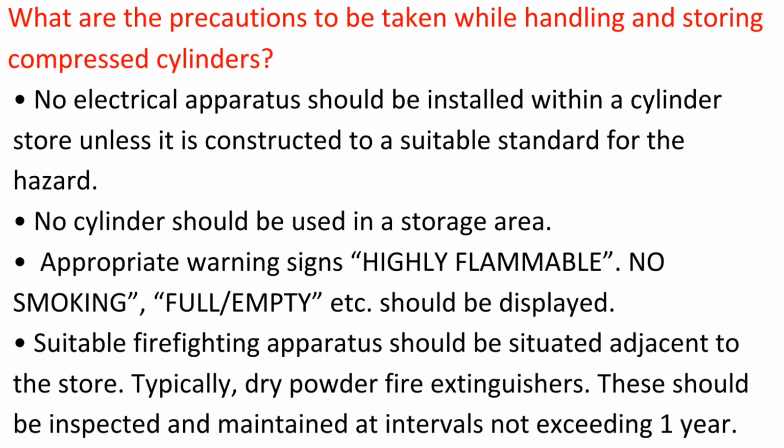No electrical apparatus should be installed within a cylinder store unless it is constructed to a suitable standard for the hazard. No cylinder should be used in a storage area. Appropriate warning signs: highly flammable, no smoking, full/empty etc. should be displayed. Suitable firefighting apparatus should be situated adjacent to the store, typically dry powder fire extinguishers. These should be inspected and maintained at intervals not exceeding 1 year.